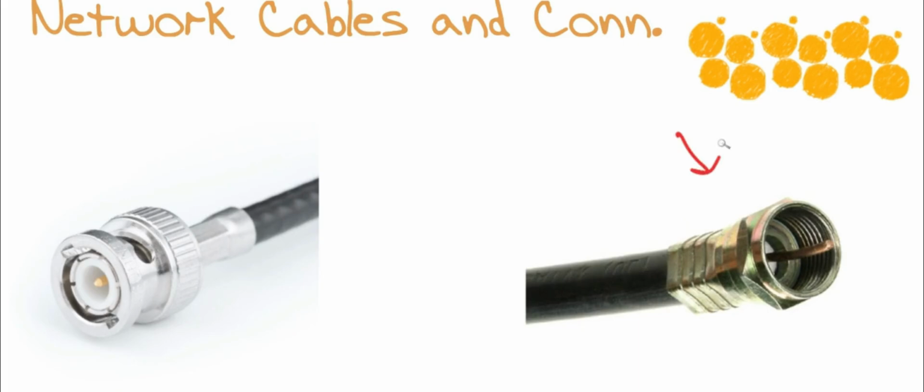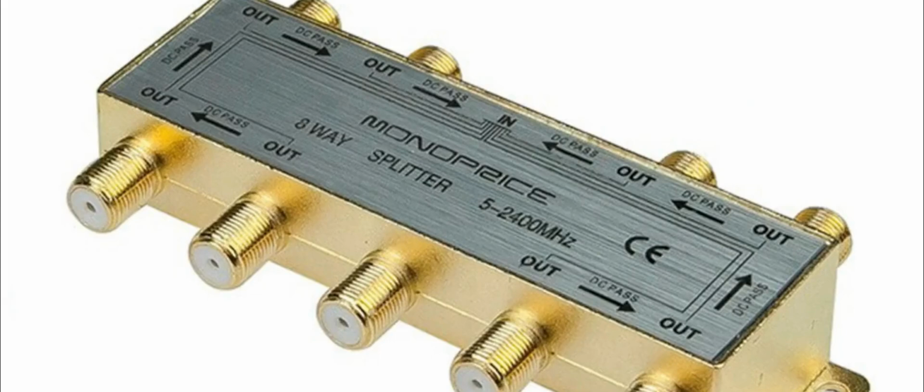Now remember, we want to use splitters oftentimes to take a cable and split it off into multiple cables, and this is certainly popular with coax. But in a lot of cable television situations, you'll have splitter after splitter after splitter, and sure enough, that can cause signal degradation once again. So many times you'll see in older homes, when you try and upgrade your technology, the cable technician will come in and he will literally eliminate a whole bunch of splitters that have been utilized and maybe even run new cable.